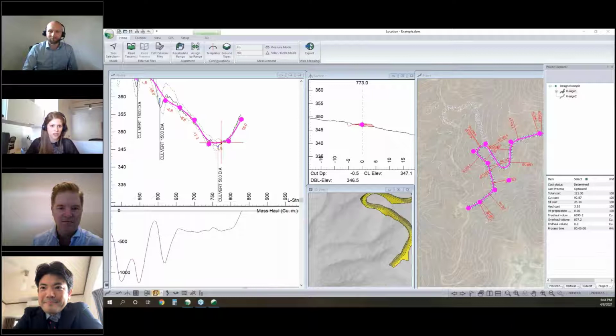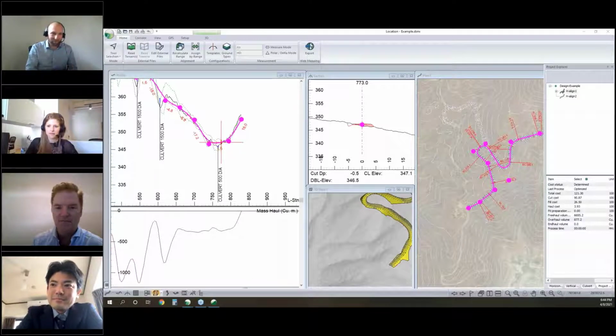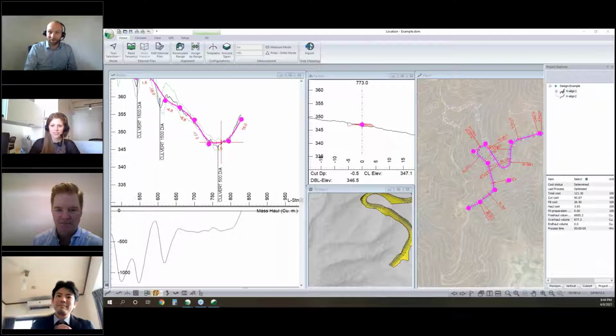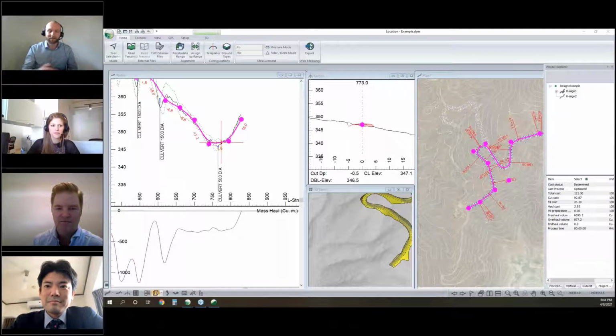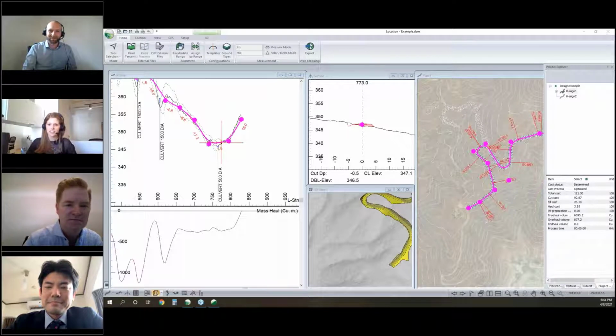And then the question asker, I think, has clarified a little bit. They said vectorizer meaning break line strings. Oh, yes, absolutely. I don't have an example set up here, but that's something we do quite well. We introduced it as dealing well with large data sets, and we also deal well with really small data sets. If you've got a site plan from a total station survey or something like that, we can ingest it really easily and format how your different break lines behave, or different lines that you don't want to behave as break lines when they come in. So the short answer is yes.